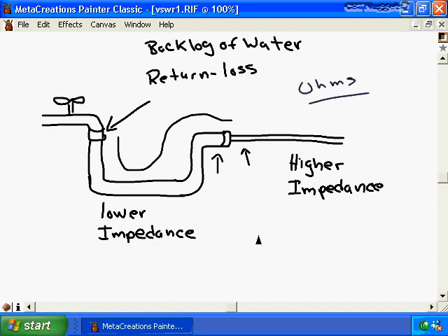Now, one of the things we have to watch out for is when we're configuring a wireless access point with an external antenna which is connected to the wireless access point through a series of cables and connectors, we have to ensure that each of the components between the wireless access point and the antenna have the same impedance level. So what we have to keep in mind is that if the impedances of the ends of the connection don't match, then the maximum amount of the transmitted power will not be received by the antenna, and because of the higher impedance, you'll find that some of the signal will actually start to flow backwards.